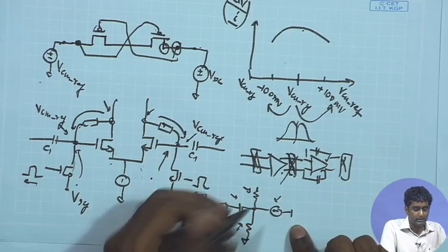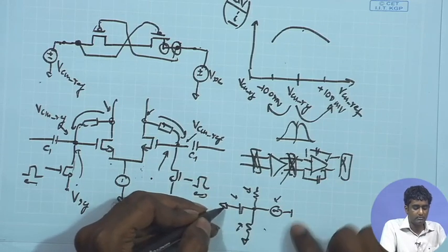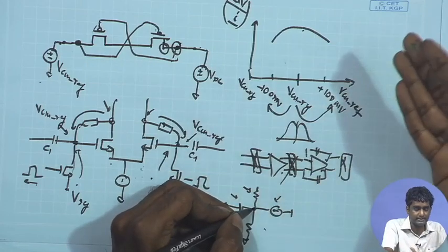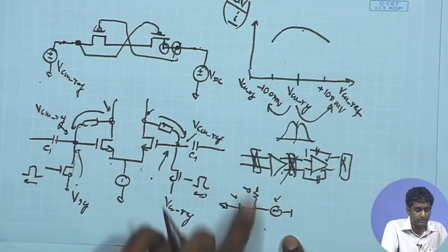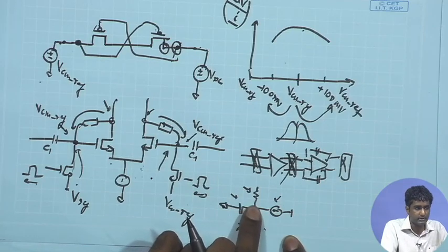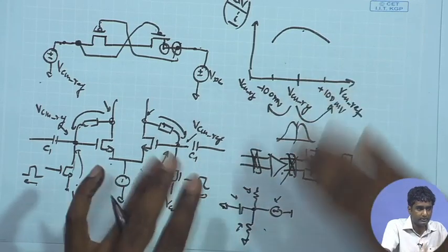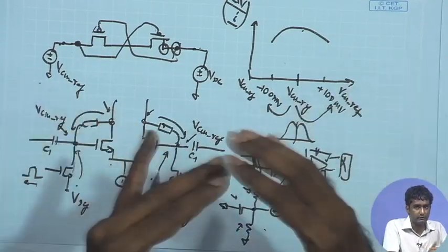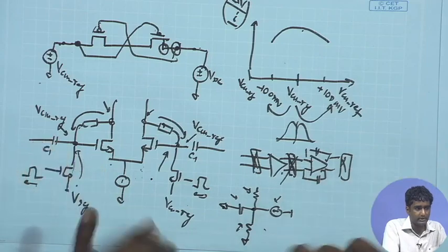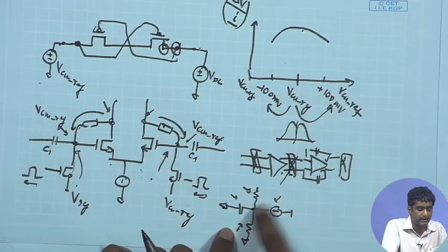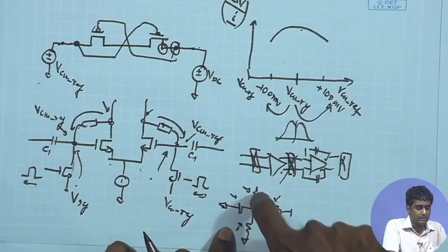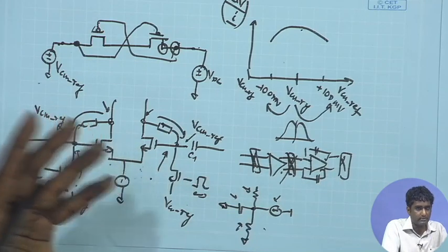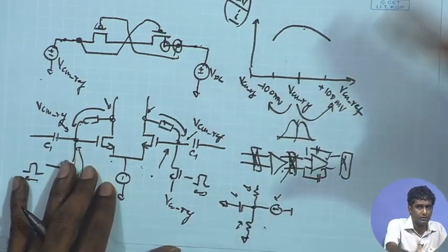As a result, once again taking the previous step values of the voltages at different nodes, it will try to solve the KCL for the next time step, taking the current values, and again find out the resulting voltage. And likewise, ultimately it forms a matrix of all these nodes. So when you solve KCL for a large number of nodes, ultimately it is a form of a matrix, and it solves that matrix for every time step while updating these capacitance values and resistance values, which are bias dependent or voltage and current dependent. So every time step it will keep solving that matrix.